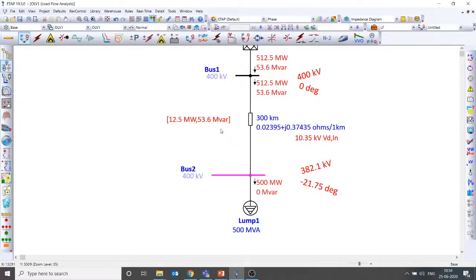The distributed slack bus model is not available in most simulation software, but there are some that support it. You can check that. And slack bus is not the only concept to perform a load flow; there are many other methods available. ETAP performs all load flow only based on a slack bus. If time permits, tomorrow I will come up with DIgSILENT PowerFactory, which has many other options to perform load flow. That's to answer Ram Natarajan.